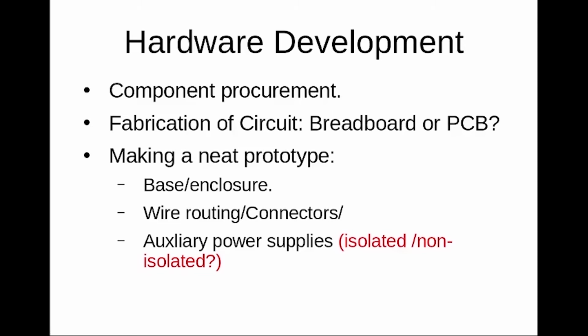Metal housing is good for power electronic converters as it would provide shielding. However, at the moment you put your converter or prototype in an enclosure, the thermal behavior is going to change. For power circuits, this could be a problem. So for power converter projects, proper heat sinking of the devices is essential, and if needed, additional fan cooling may be provided. So please refer to the thermal design sections described in power electronics textbooks for understanding and designing heat sinks for power devices.